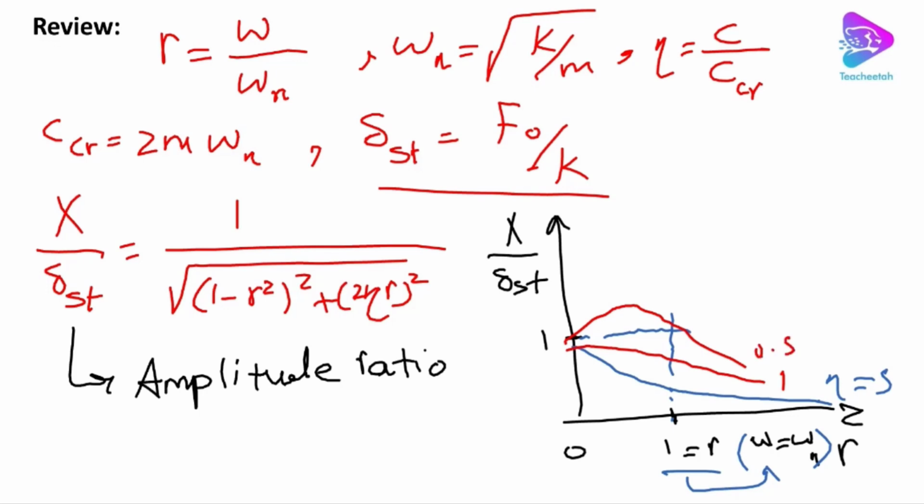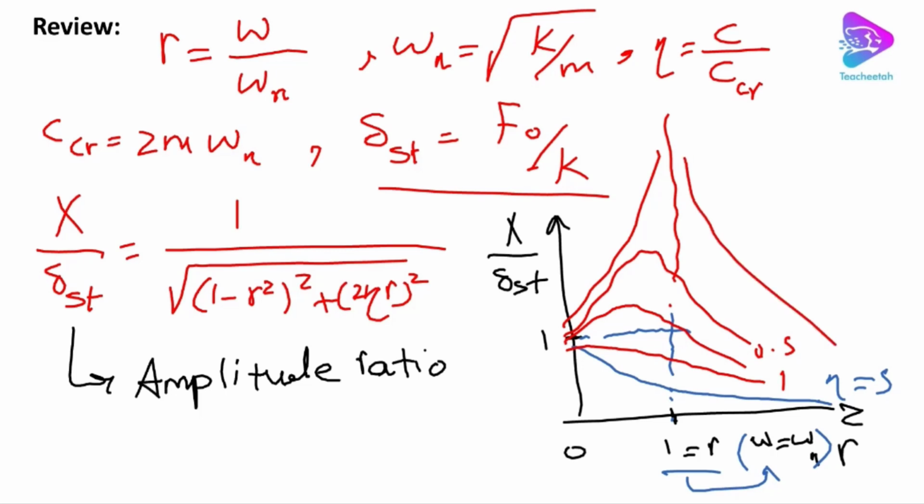and then zeta becomes smaller, and at a very small amount of zeta, the system has a very huge amplitude, which is a sort of resonance condition, for example 0.1. So remember, it is very important to know how big zeta is, and based on that your behavior would be different. And as you see, when R becomes larger, the amplitudes tend to go to a small number, and also go asymptotically to a constant value.